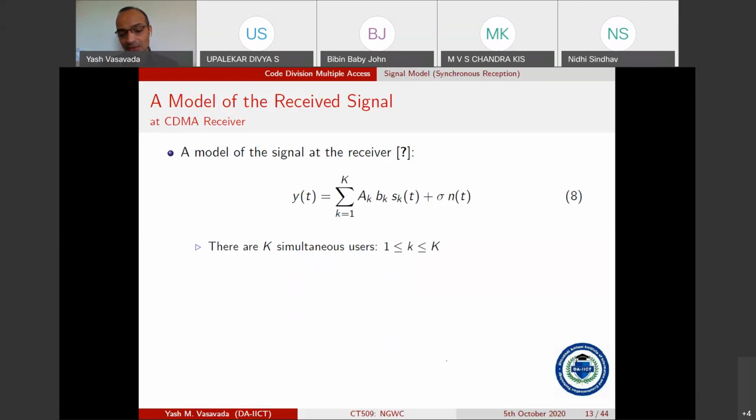But in this new technique, which is considered as the futuristic 5G technique, the idea is to do non-orthogonal multiple access. We intentionally allow some interference among different simultaneous transmitters. And unlike maybe what our human brain can deal with, the idea is that we would employ some very sophisticated algorithms at the base station to remove the interference from these simultaneous transmitters.